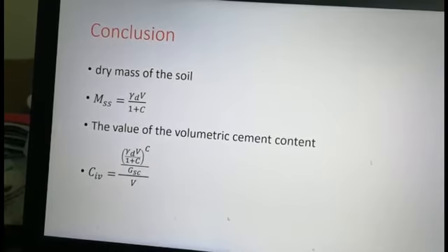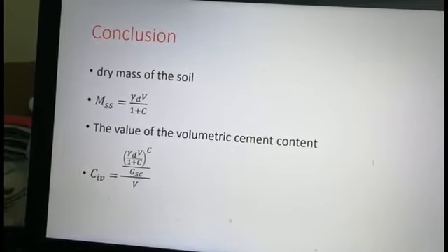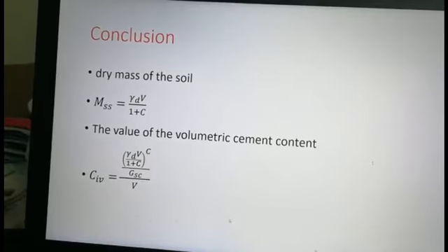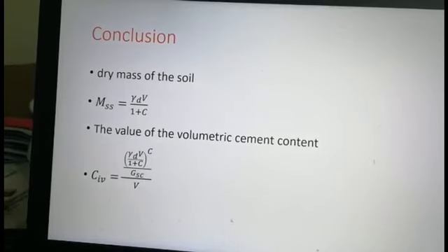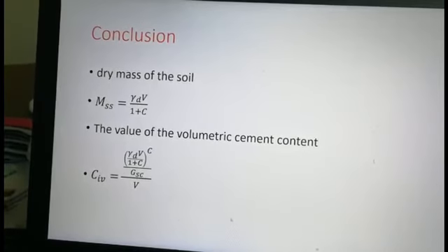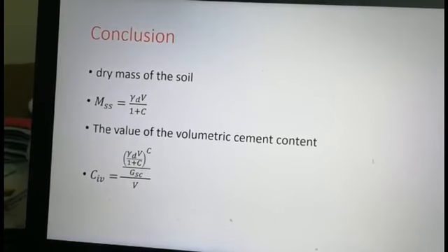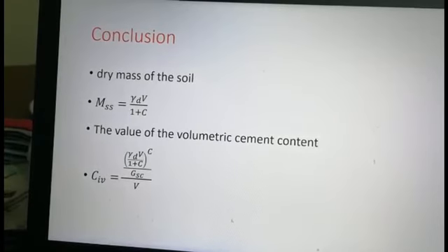This soil can be mixed with various contents of cement in order to establish different options for the cement content combination to reach the 2000 kPa unconfined compressive strength. The porosity cement ratio needs to be defined.